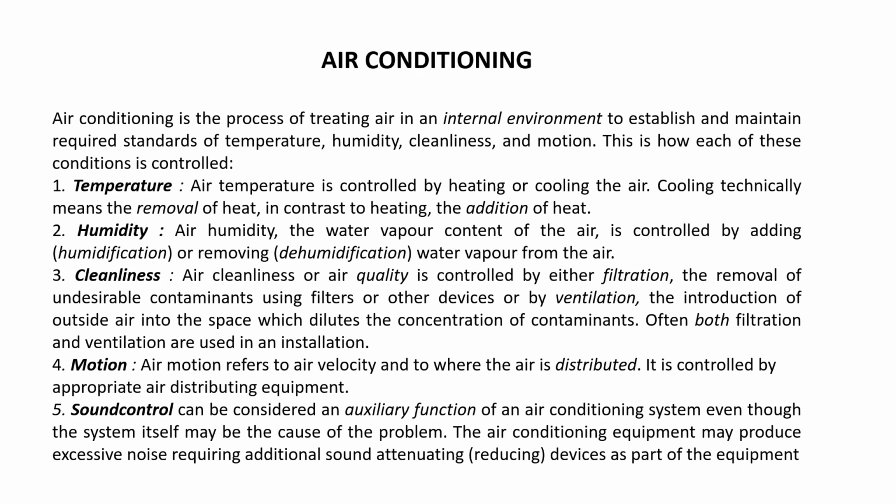Cleanliness means we improve the air quality either by a filtration process, that is, the removal of undesirable contaminants using filters or other devices, or by ventilation, the introduction of outside air into the space, which dilutes the concentration of the contamination. Often both filtration and ventilation are used in the installation process.